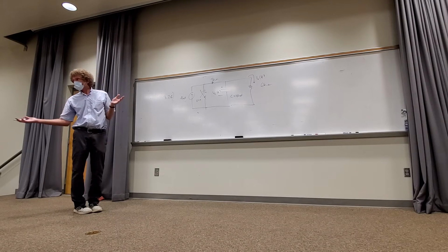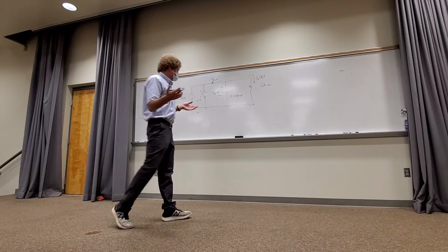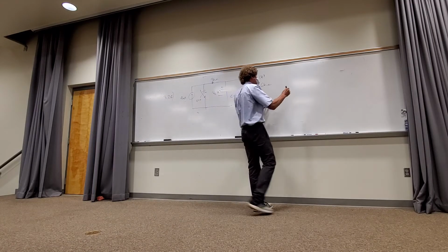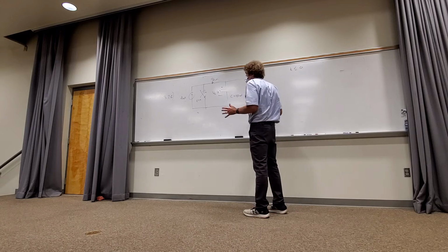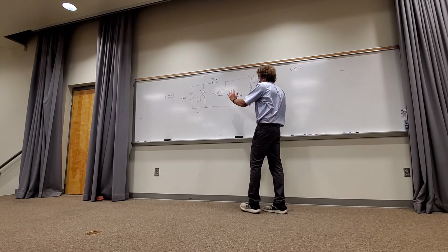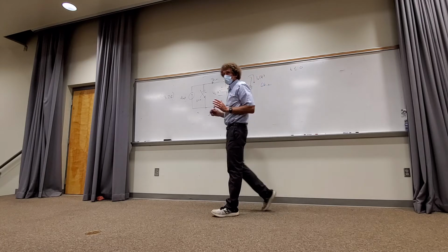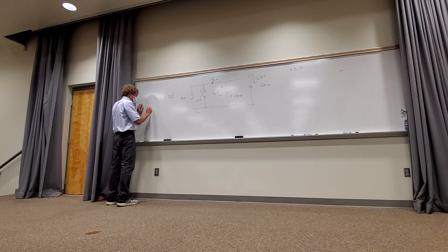All right. Now, work with me on this one, and force yourself to think critically about it. All right, what are the steps? For t less than 0, I look at what the circuit looks like. Now just listen, don't think. This looks like an open circuit, right? So I'm not even going to put the capacitor in there. I'm going to go ahead and put that current source.